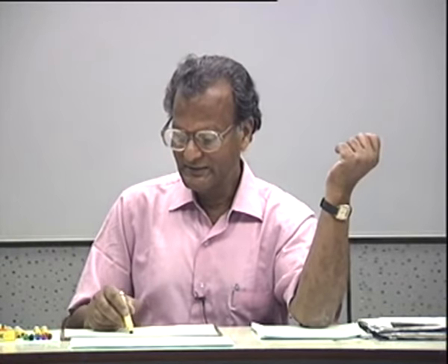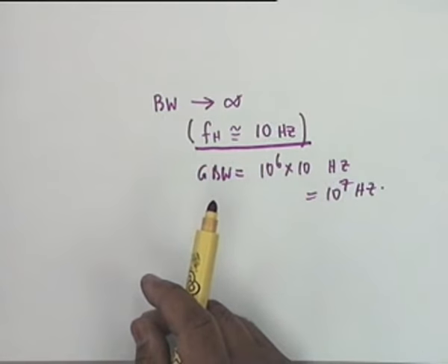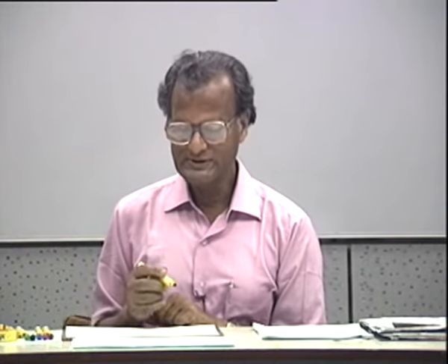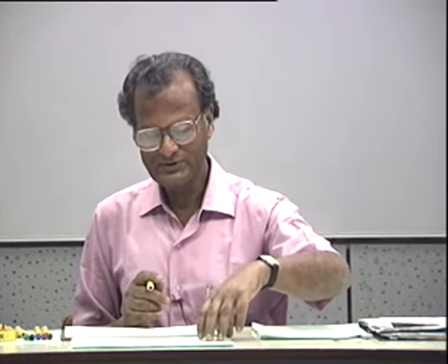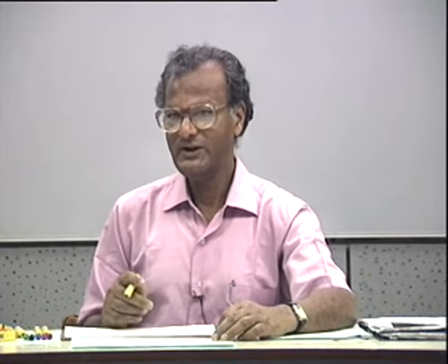But the high frequency 3 dB point of necessity has to be reduced to a few tens of hertz. Even if you can design an op-amp with differential amplifiers and other stages, we will come to the architecture a little later, but of necessity it has to be reduced. We will see what the necessity is. We also assume that the input differential amplifier's transistors are perfectly matched, which never is the case.